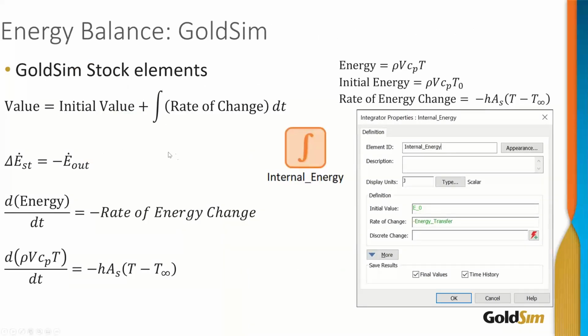Okay, so now that we understand the concepts of the energy balance of a body changing with respect to time, and now that we understand the thermal equivalent network, we're now going to talk about how this relates to GoldSim and how we model this using GoldSim. And the element that we're going to use is a stock element, particularly the integrator element.